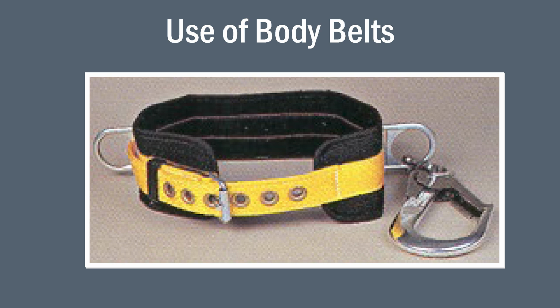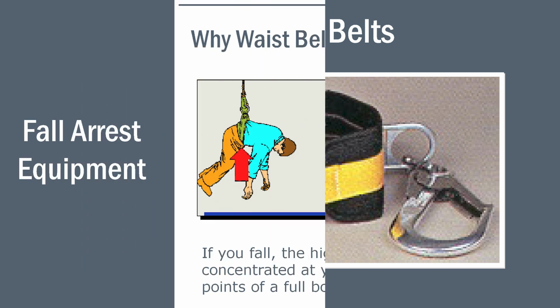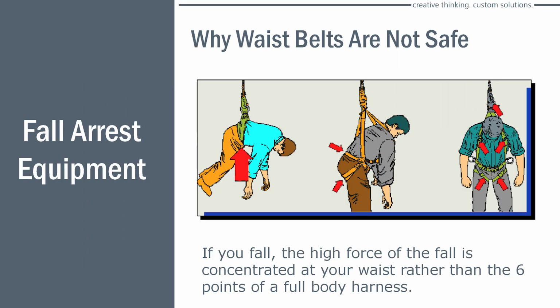And this is what I'm talking about, a body belt. Now, body belts can still be used, okay, but not for a fall arrest system. And I'll show you that in a little bit. This next picture shows you what could happen if you are in a body belt. See how all the forces are applied to the midsection compared to when it's evened out over the harness.